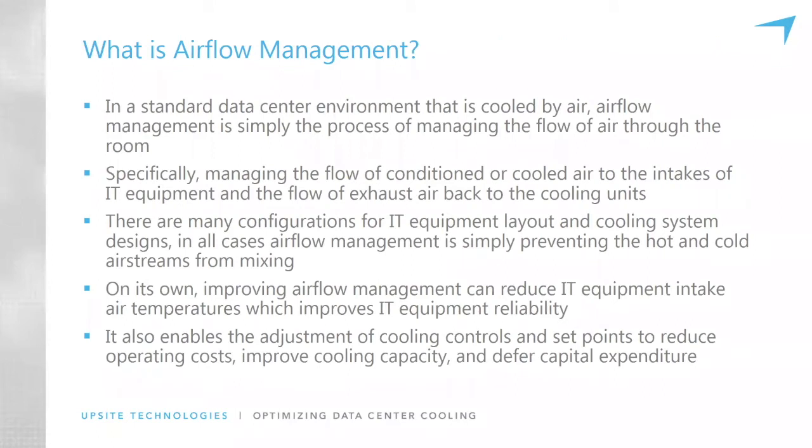So let's look at a few of these different aspects of airflow management, because it all begins with airflow management, all the way out to free cooling and economization and data center design. It all begins with fundamentals of airflow management, and with those maximized, all the other aspects of data center operation related to cooling improve. So in a standard data center environment that is cooled with air, airflow management is simply that process of managing the flow of air through the room, all the way through the room in the complete circle. And it's specifically keeping the conditioned air separate from the exhaust air.